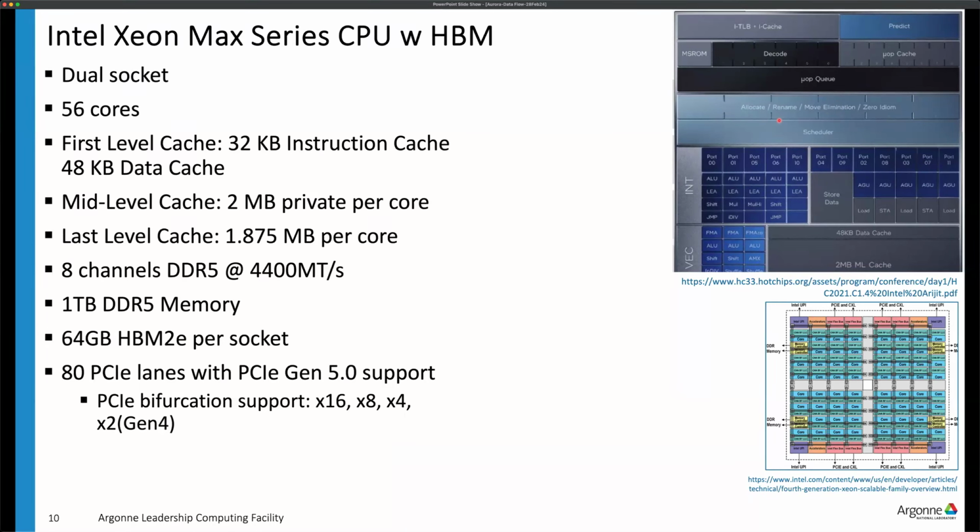So typically, when CPUs are presented, the application-side view is that they have distinct compute components, like the different ALUs and the vector units and the caches, and they tend to be put together into a monolithic die, right? The Xeon CPU Max Series, codename Sapphire Rapids, is actually composed of distinct dies that are put together. There is a diagram here. I will talk more about the diagram in the later slide deck, but just keep in mind that it's not simply a component distributed over a standard monolithic die.